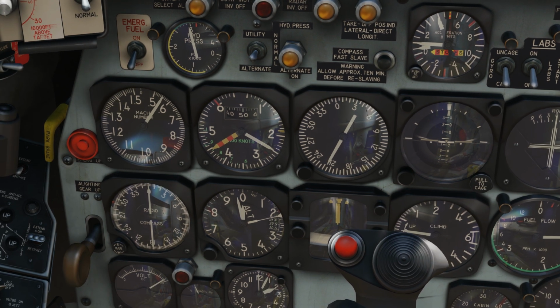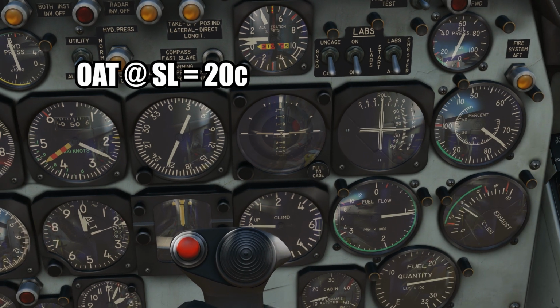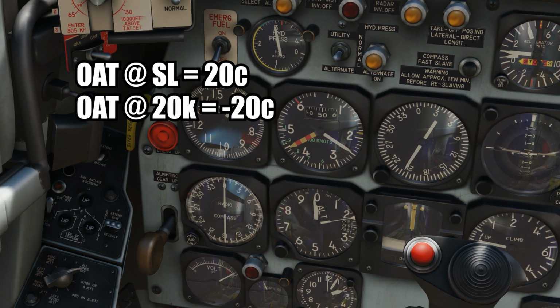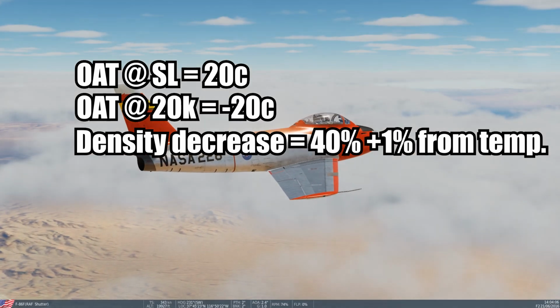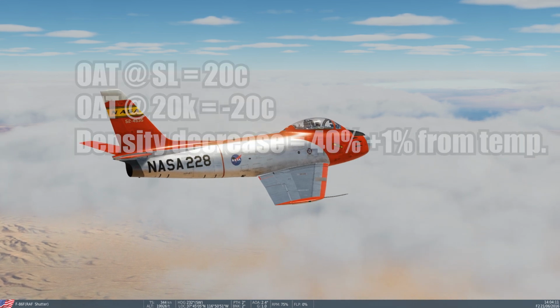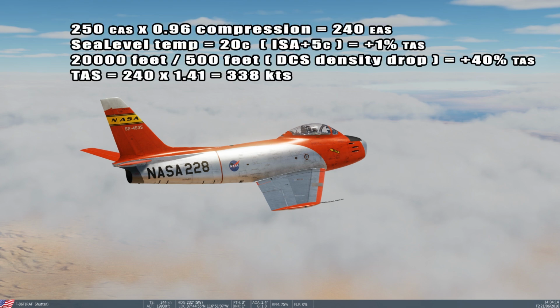If we take as an example the standard for DCS missions, 20 degrees, which means a plus 5 degree ISA deviation, with a standard barometric pressure, at 20,000 feet we have a 40% increase in TAS from altitude, and 1% from the temperature, resulting in a 41% increase. We will assume a compressibility correction of 96%, as this would vary with many factors. At 250 knots of calibrated airspeed, times 0.96 equals 240 EAS, times 1.41 equals 338 knots of true airspeed.